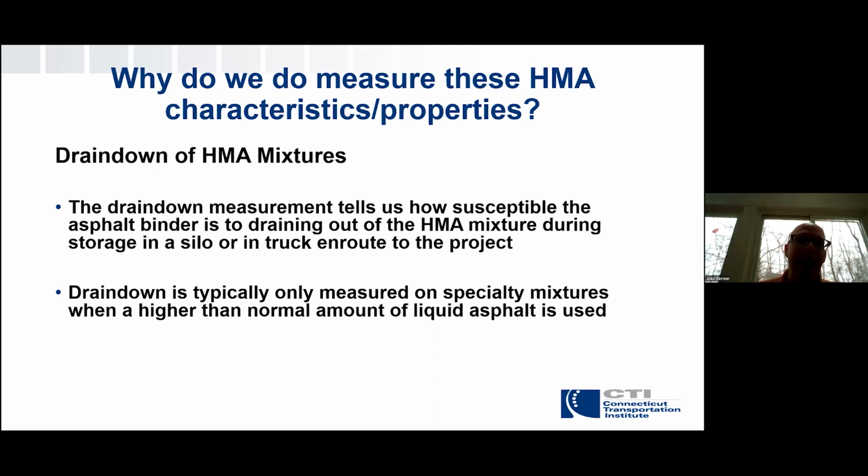And these have a higher asphalt content because there's less stone in them. And we put less stone in for two reasons, actually, or we put more asphalt in for two reasons. So when we have these open graded or gap graded mixes, we not only have less particles to coat with the asphalt, but we need that asphalt to help hold it together. Usually a dense graded mix has more stone on stone contact that's locking. It's called particle interlock of the stone matrix. But anyway, we need to monitor this and make sure they're designed properly.